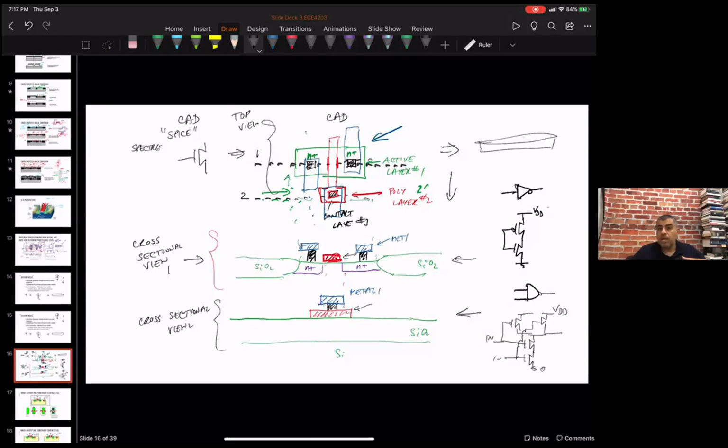And the reason you have a bunch of metal interconnections is if you just had one layer, imagine trying to connect up a billion things with one layer, pretty quickly you'd block yourself off. So you basically jump between layers to jumper across up and down to be able to make connections.